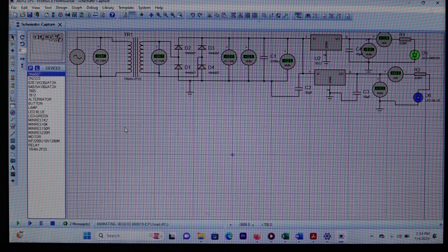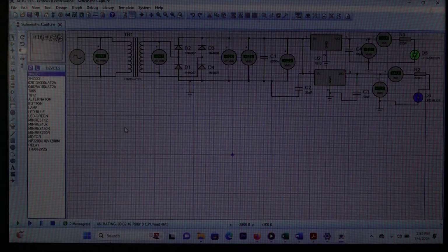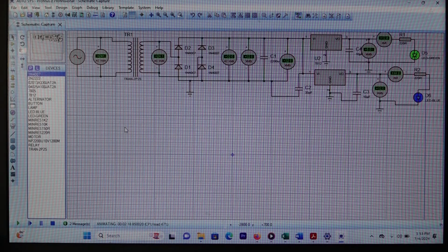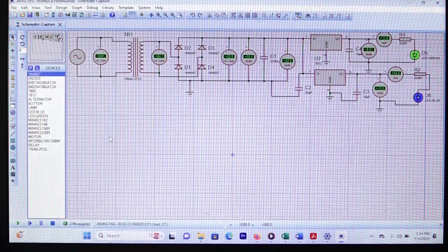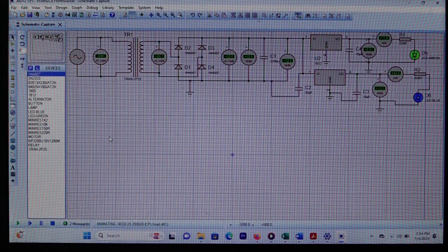The remaining blocks are, first, the digital sensor unit, where we are going to use either a pull-up resistor network or a pull-down resistor network. For this case, we are going to use a pull-up resistor network, which will work similarly to how the IR sensor is used to detect the presence of an obstacle. The second block that we are going to open is the NPN bipolar junction transistor switch, and afterwards we'll open the block of the relay switch. Then finally we'll open the block of the loads.